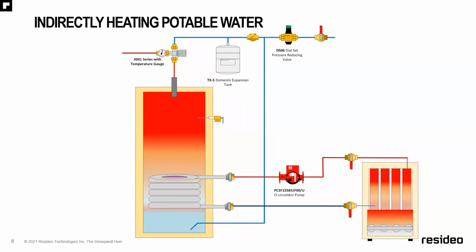Now you can even get better. If you have a wall hung boiler, those high efficient boilers, you're even maximizing that turn down ratio. If you have a system with a 15-to-1 or a 10-to-1 turn down ratio on a wall hung boiler that's super efficient, you're really going to be doing your customer a favor by adding a domestic water heater and consolidating these two features.